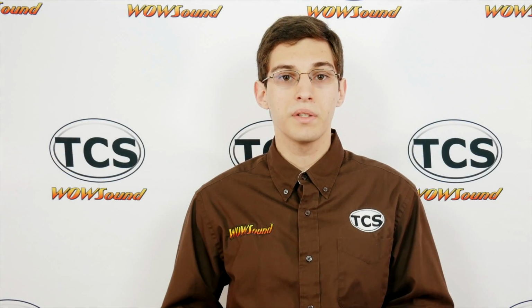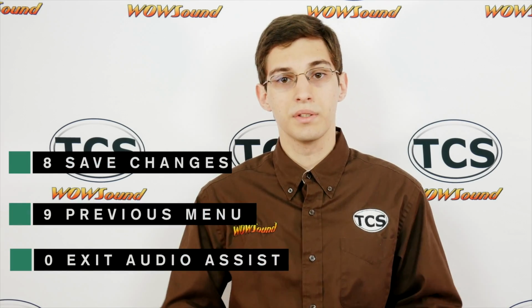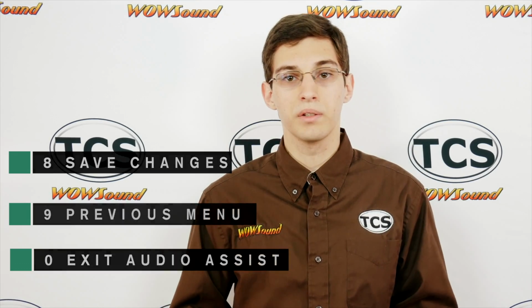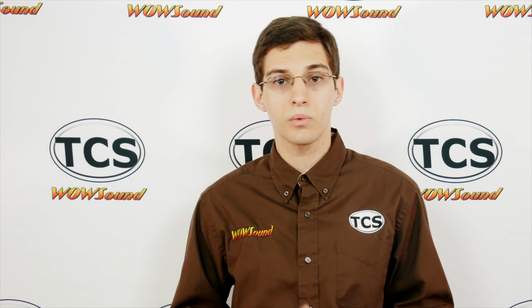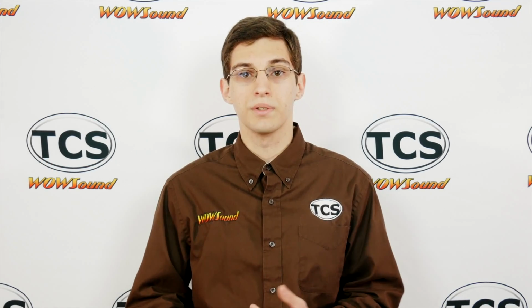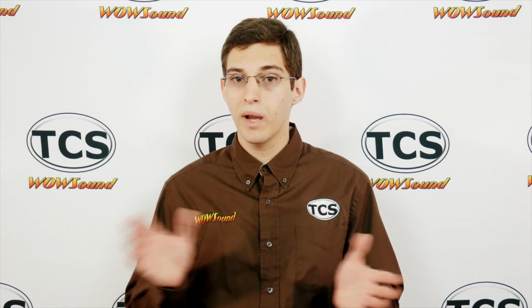The most important buttons to remember when using Audio Assist are button 8, button 9, and button 0. When making changes in Audio Assist, you must remember to save those changes by using button 8. If you do not save your changes before exiting Audio Assist or switching between menus, your changes will be discarded. An exception to this rule is the automatic calibrations. When performing an automatic calibration, these changes are saved automatically.